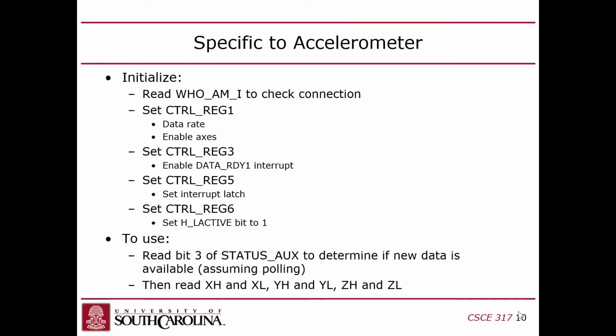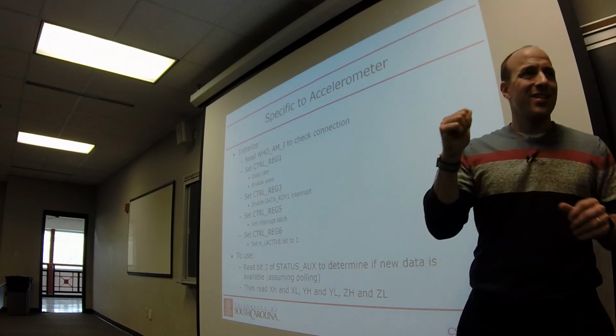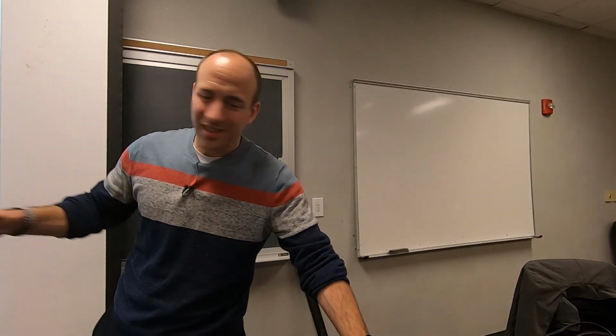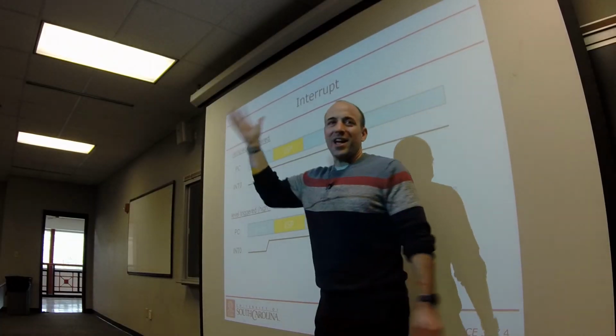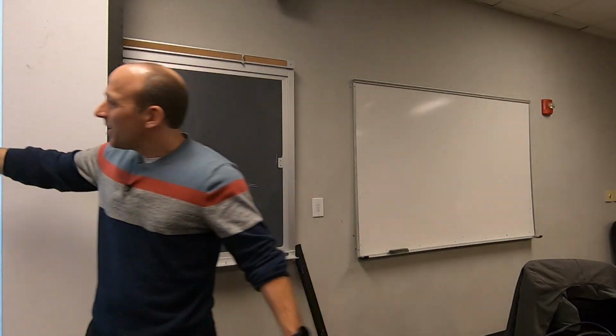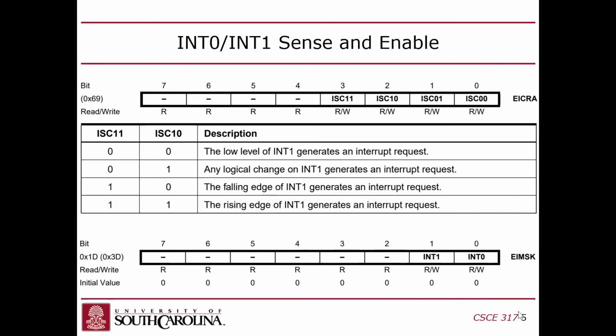So the one in Control Reg 6, normally it would pull it active high when there's an interrupt. Yes, that inverts it. Yes, okay, thank you. It took me forever to figure out over Christmas break. I remember. That references back what I was just talking about. The interrupts are tricky with this little guy. If you don't do all three of those things, you're not going to have a good time.